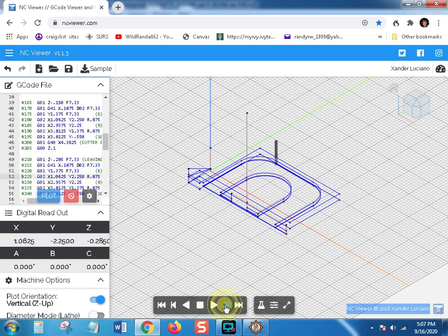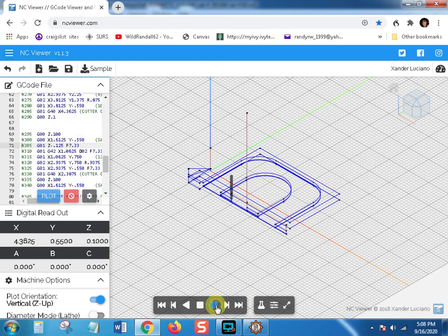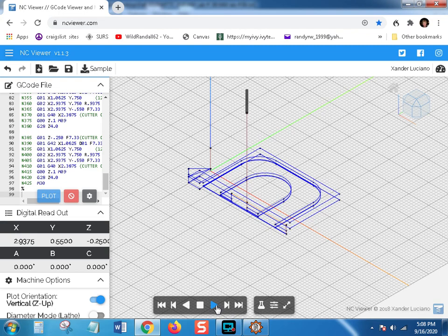Now you're saying this looks exactly like it did before. Yeah, it does. But when you put those D numbers in it and you populate the tool geometry page of the control, all right, I'll just spin that all the way to the end. When you populate that with, first off, D02, you're going to put in 1 inch and 30 thousandths is the diameter of the end mill. For D01, you're going to put in 1 inch. You're going to actually use a 1 inch end mill. D02 will stay away. So that is a beautiful way of programming stock, and this is a viable part now. For all practical purposes, it's very viable. I might go over it. There may be a couple little things I might want to optimize, but it looks really good.